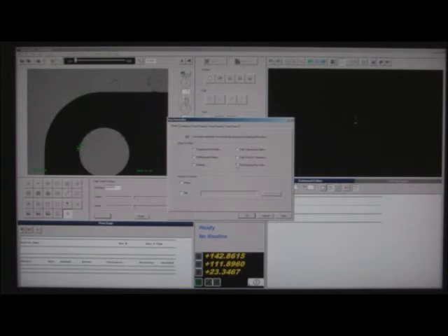So maybe we measured the surface finish on a profilometer, but you want that information in the inspection report with the part. And we can have a manual data entry step that will let the operator put in whatever value he measured during that surface finish measurement and have all of the data in the same file. Again, print elapsed run time will let you know exactly how long each one of the runs lasted.